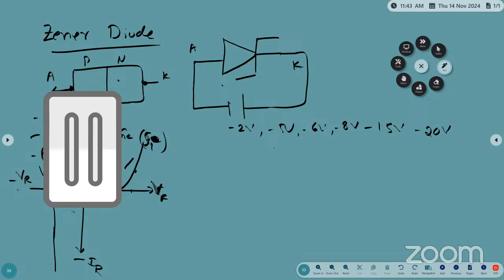What did you observe here? If you increase the biasing voltage in the reverse bias, the voltage across the diode stays the same. How do you measure the voltage of a component? In volts, using a voltmeter. How do you connect the voltmeter to the component? Parallel or series?